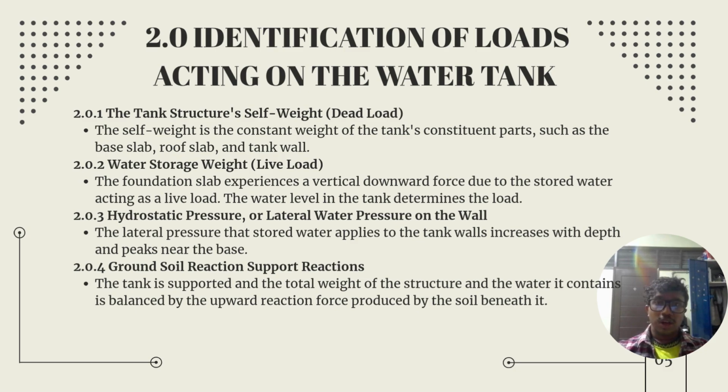Thirdly, hydrostatic pressure or lateral water pressure on the wall. The lateral pressure that stored water applies to the tank walls increases with depth and peaks near the base. Finally, ground soil reaction, support reactions. The tank is supported, and the total weight of the structure and the water it contains is balanced by the upward reaction force produced by the soil beneath it.